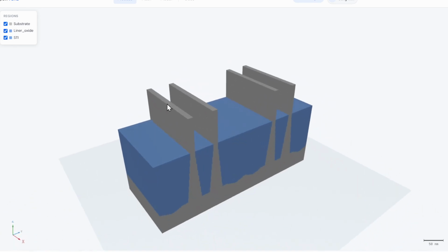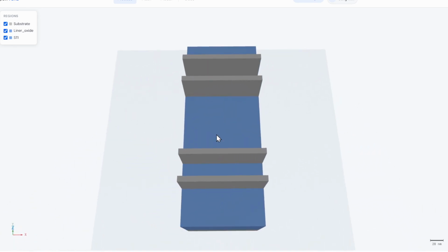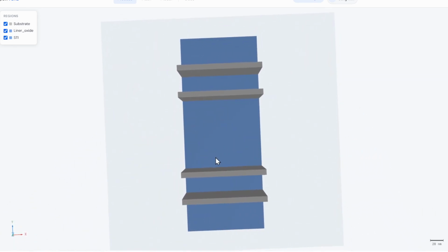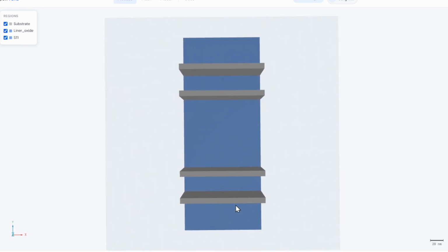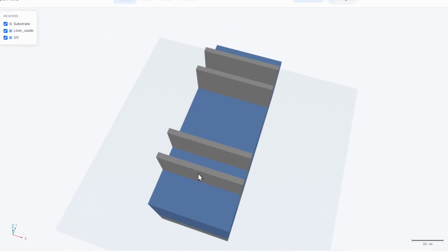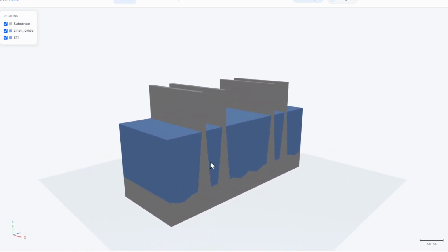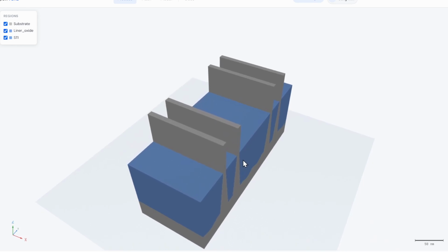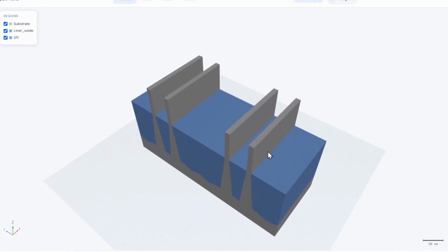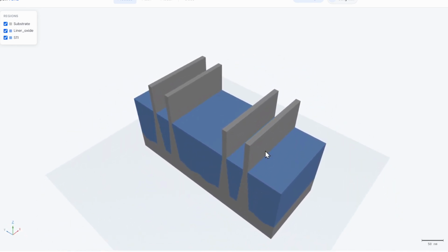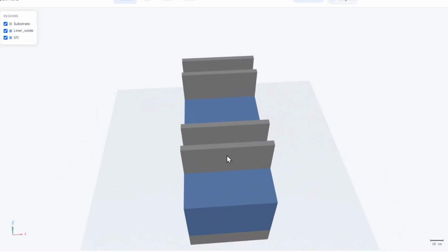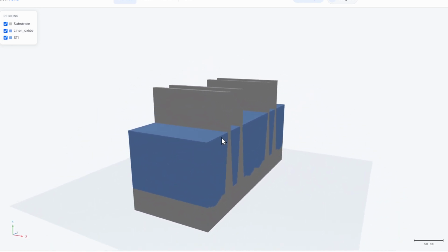So as you can see once again, if we take the top view, we can see the part for the N MOSFET and the part for the P MOSFET, and there are two fins, and their isolation is done by this STI, and still we don't have any structure like a gate or source and drain. That will be done later.